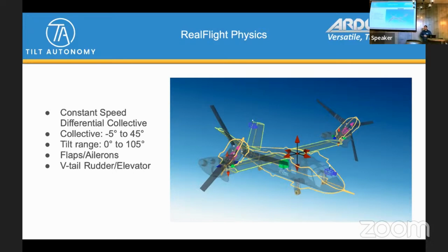That's right. A great example of that that I did recently for a partner was the E-Flite Convergence, the tricopter tilt rotor. Their airplane's very similar to that, almost identical, but with different dimensions. Due to their construction, they couldn't get the CG far enough back onto the VTOL motors, and they were wanting to prove out, is this sufficient?